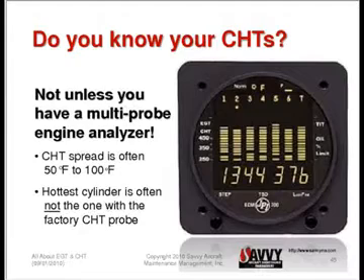The standard factory instrumentation that until recently used to come with most of our airplanes only measured the CHT on one cylinder. There was no guarantee that CHT was the hottest one, and you had one chance out of 4 or one chance out of 6 of catching a cylinder problem, because you were only looking at one cylinder, not all of them. So anybody that flies a piston aircraft without a probe-per-cylinder engine monitor is groping in the dark.